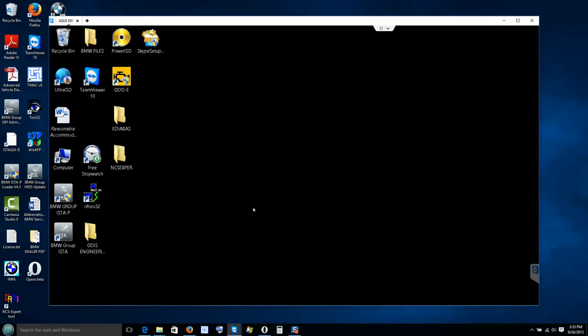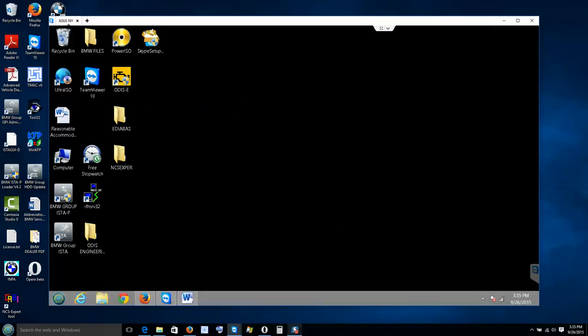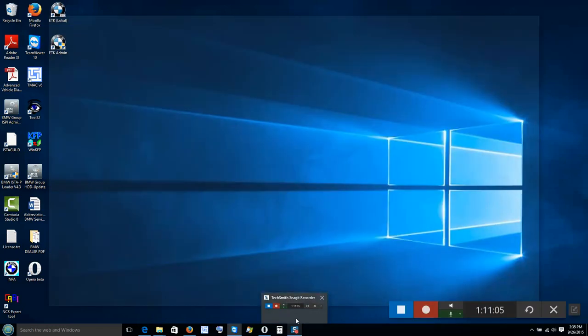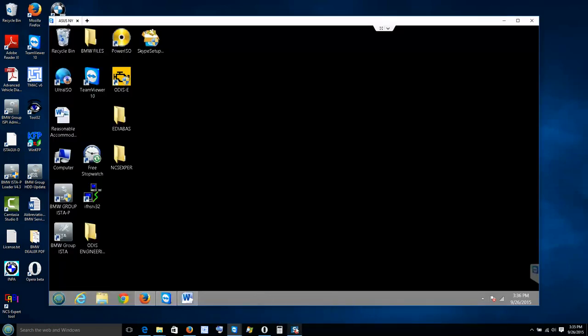Unplug the icon for me now for about a minute. Just unplug it for now, okay? Okay, this one is the SC on an E39. We replace the unit and we do a steering angle sensor calibration, and we also do a lateral transverse calibration, and we also do an angular calibration, and we also do an end of line test to remove the three lights from the dashboard. So I think it takes us this long to accomplish it. So this is just a basic tutorial of how to repair those systems.